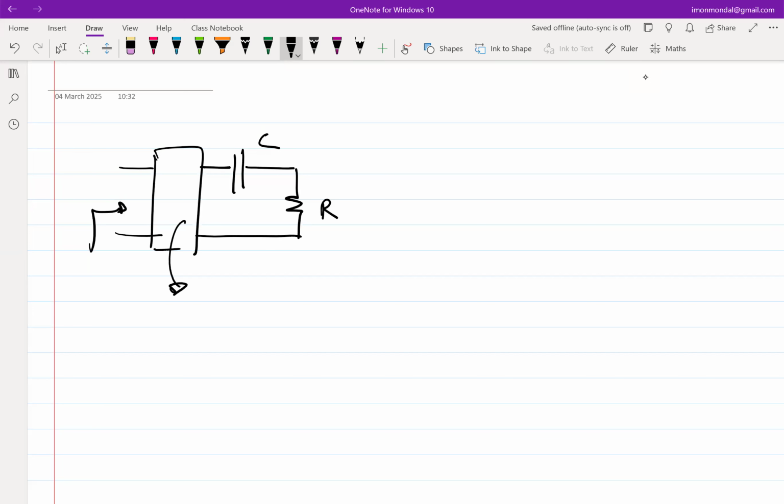So if somebody asks me this, then obviously the first thing I'll do is, it looks like a multiple choice, right? I can only put R or L or a C. So let me see, can I put an R? Obviously, R will not make any sense, because even if I put an R, if I look from this port, let's say this is 1 dash, I'll basically get some value of the capacitance, which will have an imaginary term. So that will not suffice. So R is out of the window.